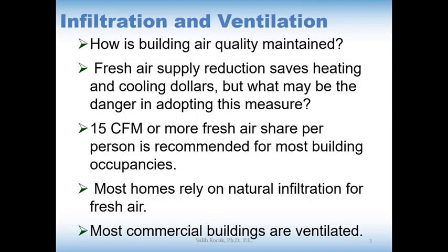So infiltration and ventilation are two ways that fresh air is supplied into the living spaces, into the buildings. Commercial buildings, since they are sealed tight to prevent the loss of air, have to be ventilated. And the residential buildings, the homes that we live in, rely on natural infiltration.